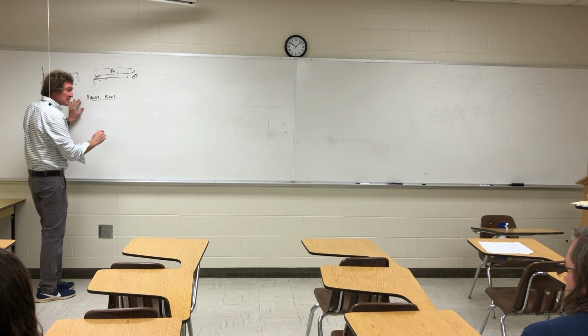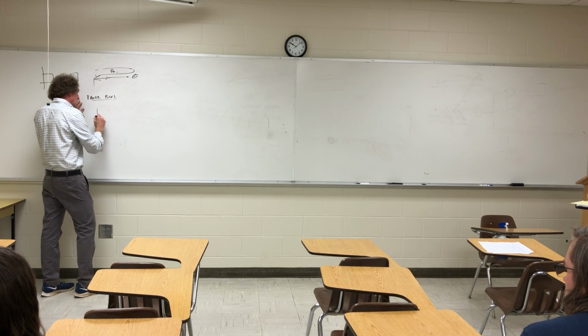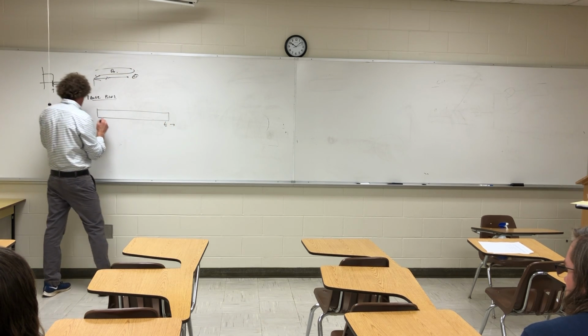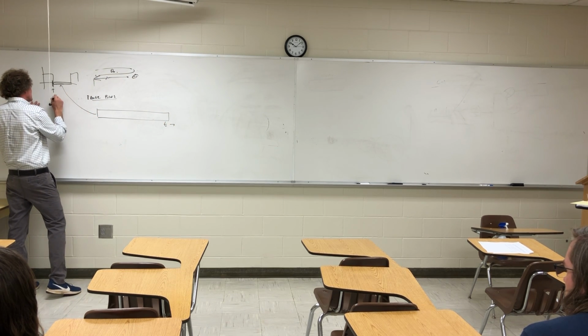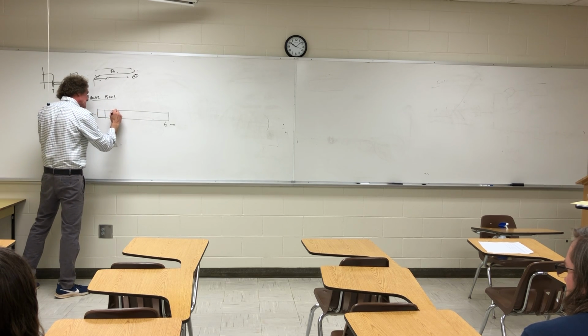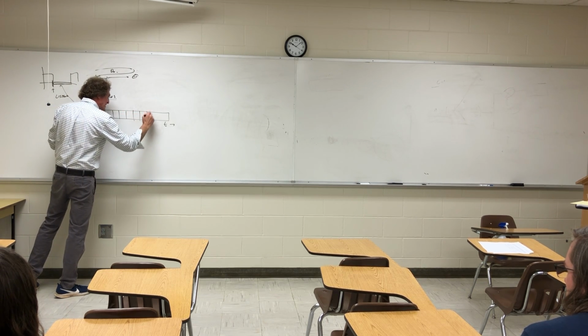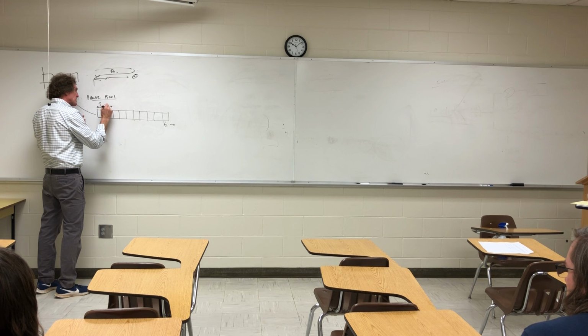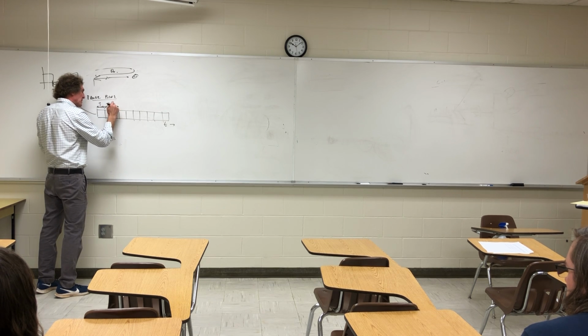And as I listen, I create a bunch of bins. If this is time, this is the range where I'm listening. And these bins, you can all follow me on this, are going to have a width of about tau. Actually, it should be less than tau, but I'm going to say they're tau. This is a range bin.